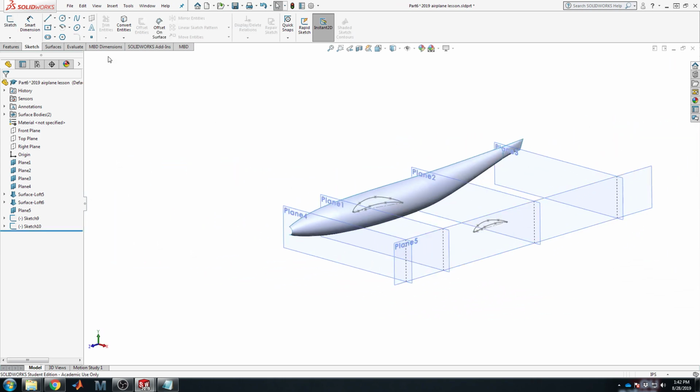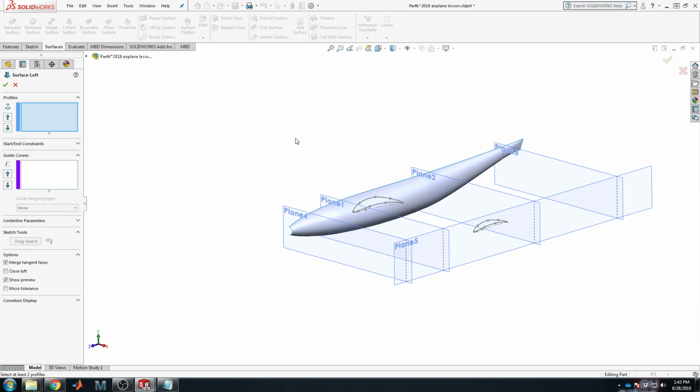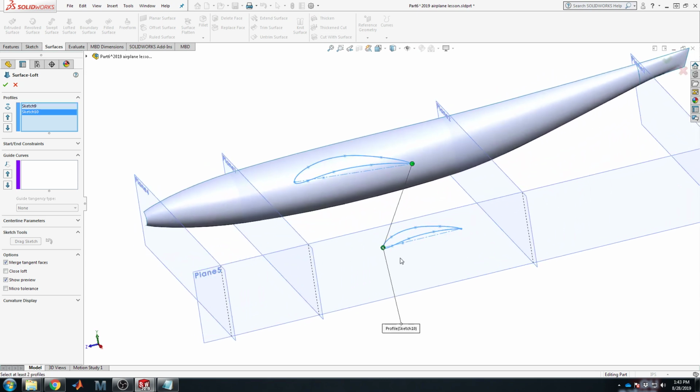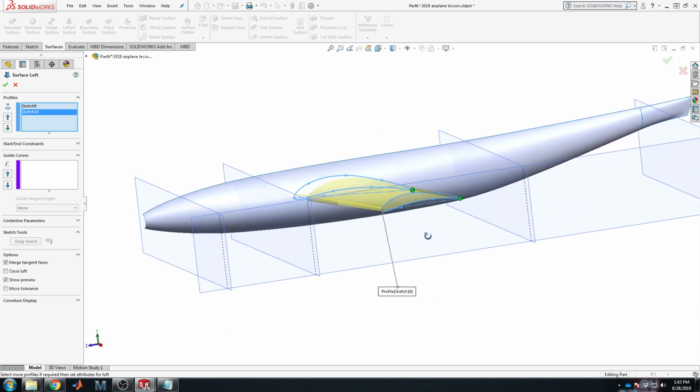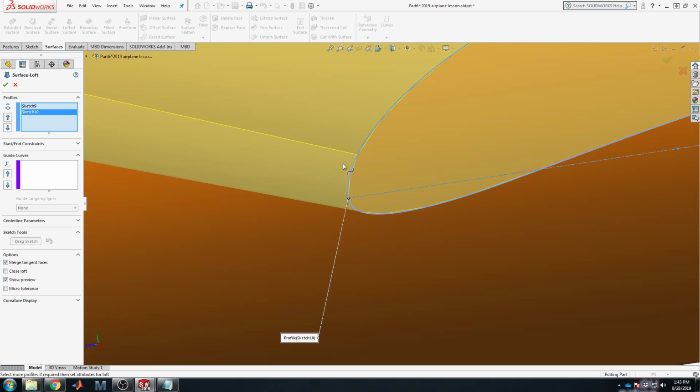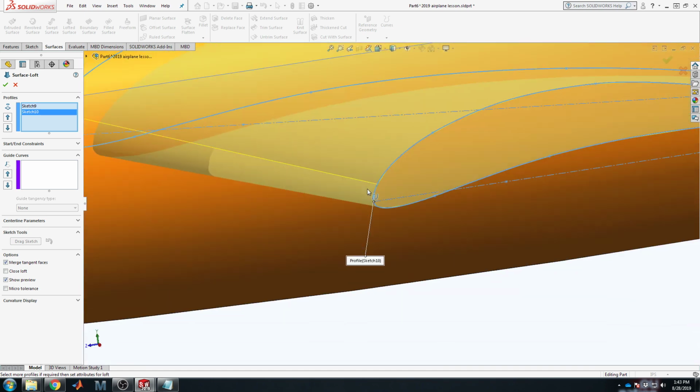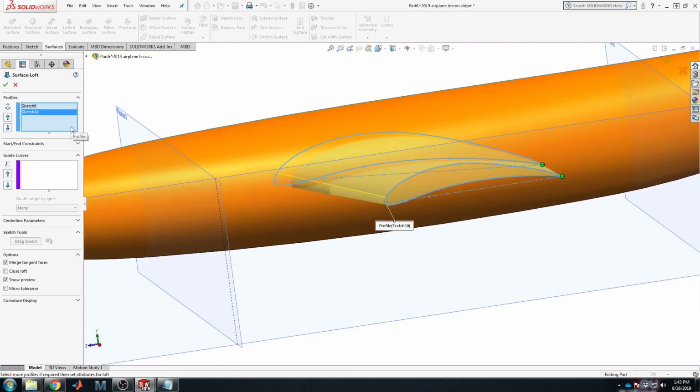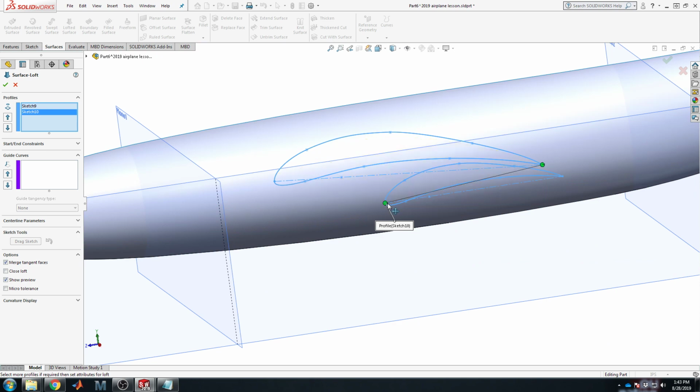So at this point, you have both of the sketches you need to make a wing. Go to Surface, Loft, and go from the root foil, hopefully, to the tip foil. Okay, it didn't show up because those closing points are on the wrong sides. I'll click and drag. Okay, that looks pretty good. Has an odd placement of that connecting point. How interesting. Let's actually put these to the front. See if that corrects that.